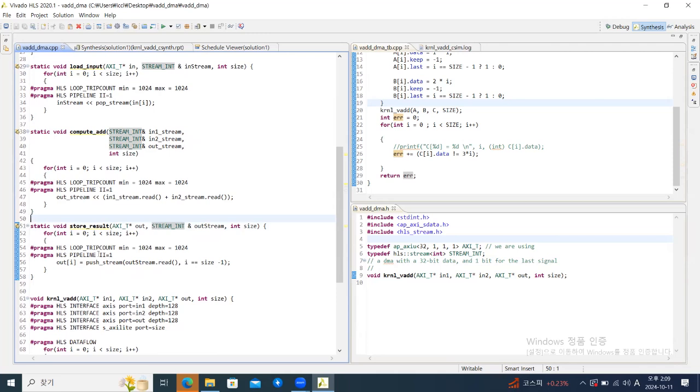In the last assignment, we had the naive version of vector add, where we had to make some C buffers to improve the performance. In that case, the C buffer is usually made as an SRAM array. In the case of FPGAs, it will be made as a bunch of block RAMs. From the hardware's perspective, that's what we call the on-chip buffer, a scratchpad memory, or just a basic bunch of SRAMs. But if you create a variable as HLS stream, it is implemented as a FIFO.